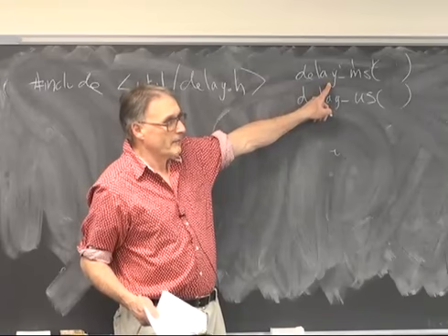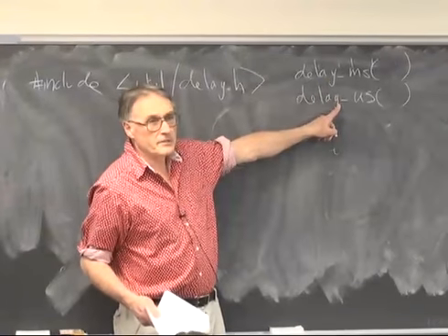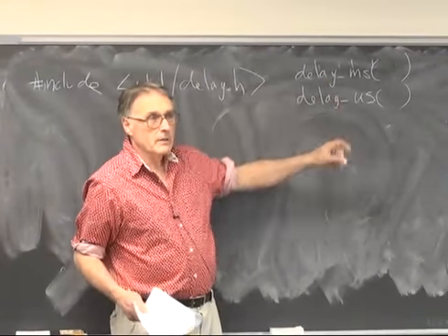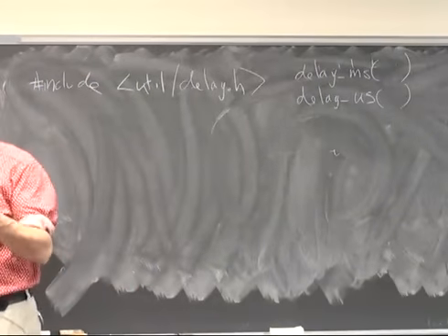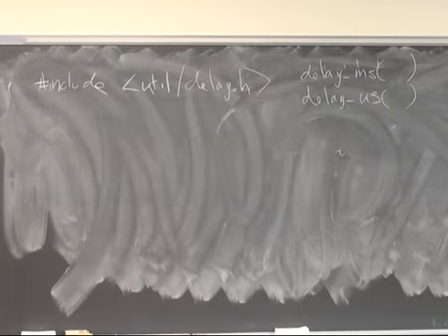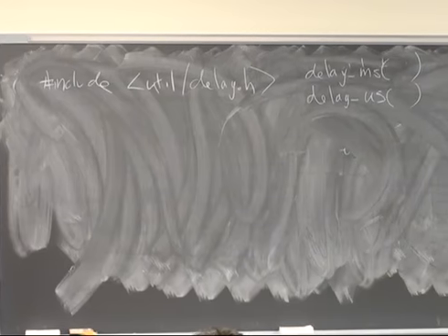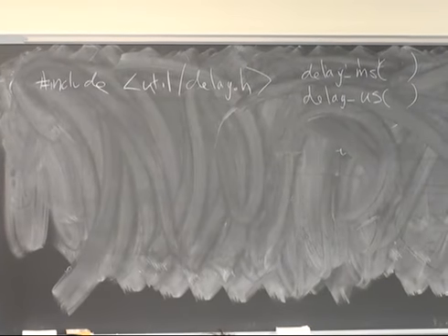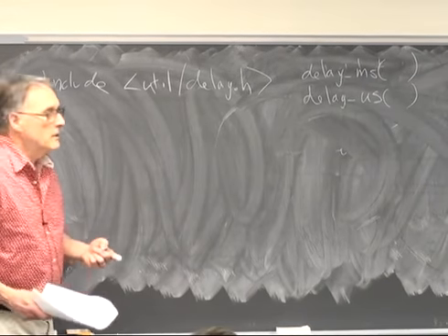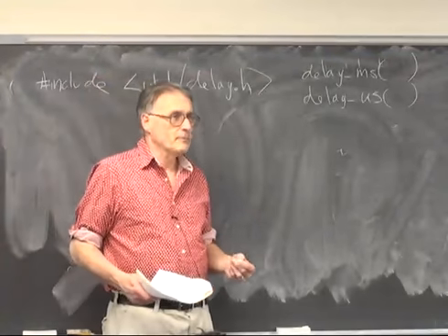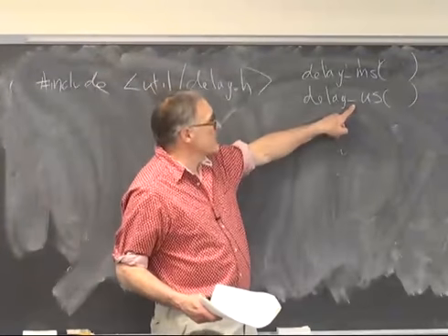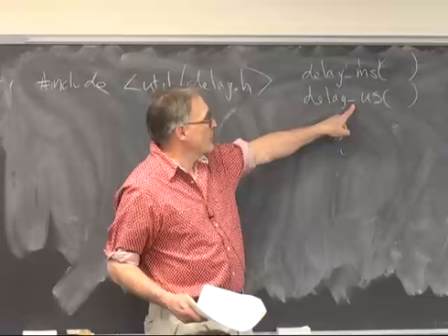Never. You may use microsecond delay occasionally because it's actually rather hard to get a few microsecond delay using an interrupt. The granularity of the CPU is not quite good enough to get a 16 cycle, 1 microsecond interrupt. So this is acceptable and is used in quite a lot of places.